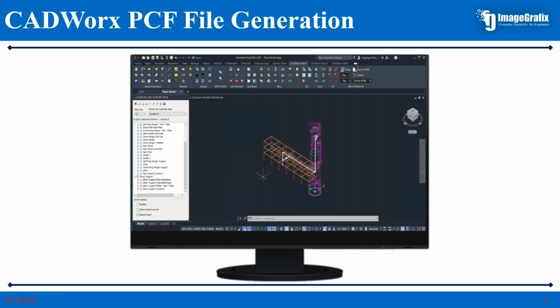In CADWorx prior to 2018, there was an option called the .c2 file, but there were some data losses such that the supports were not transferred properly. To overcome those issues, in the latest version we have something called C2 PCF, with which, along with your pipe support data and pipe model data, you can even transfer your process data, like temperature, pressure, design pressure, operating pressure, or any other temperatures and pressures you want to take along with your details. That can also be transferred along with your PCF file.